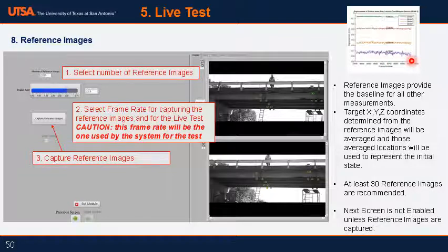Usually when we're calculating strains or relative movements, we take the first frame and say, okay, this is my zero point, and I'm going to calculate numbers from it. But if it's up or down or anything within that noise, you're not going to get a really good zero benchmark or zero deformation state.